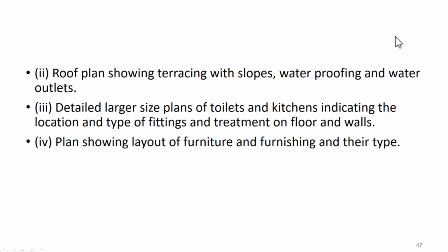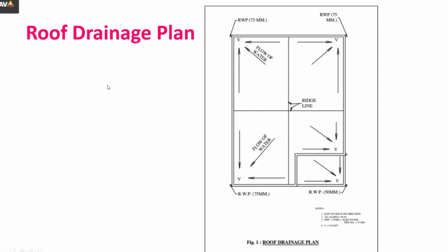Let's move ahead. Yes. Now we say that the main entrance to the plot. Now suppose there is a plot and there is some entrance we need to give to this particular plot. Now the gate provided for that particular plot should have adequate width to allow easy access of the fire engine, and in no case not less than 6 meters. So you cannot have a gate of 3 meters. Although you have provided the entire space of 6 meters in and around the building, if you are providing 3 meters, obviously the fire tender cannot enter. So I need to have adequate gate width of minimum 6 meters.